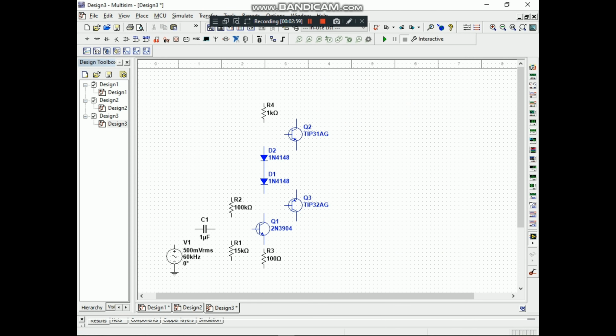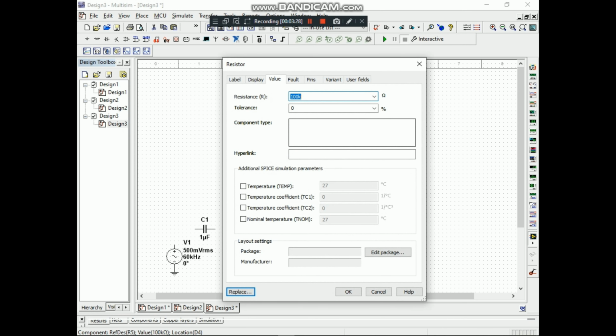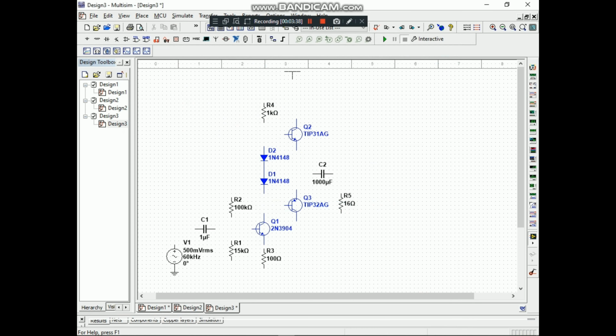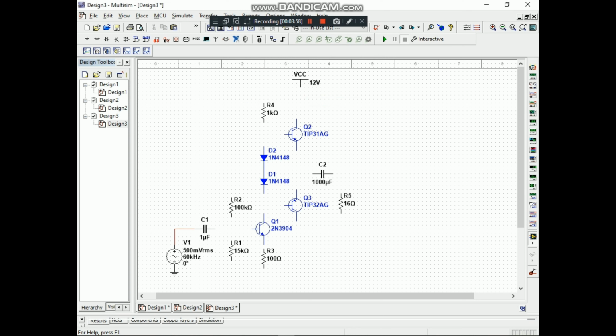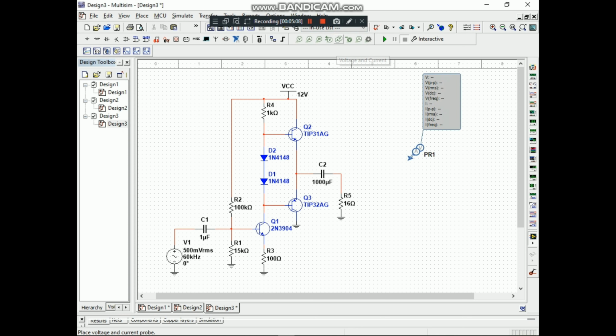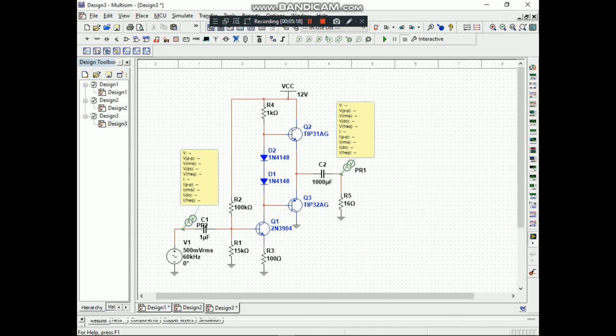As the input signal drives the base of our first transistor, it acts as an amplifier stage driving the base of our NPN and PNP, with the positive half of the input cycle driving the NPN while our PNP is off, and the negative half cycle of the input driving the PNP while the NPN is off. The implementation of a Class AB amplifier is very similar to the standard Class B configurations, in that it uses two switching transistors as part of a complementary output stage.